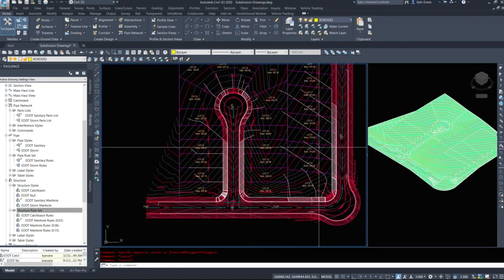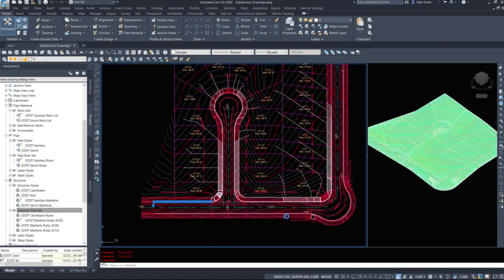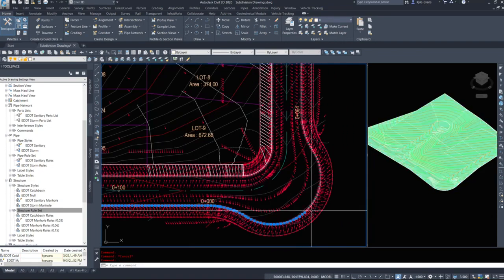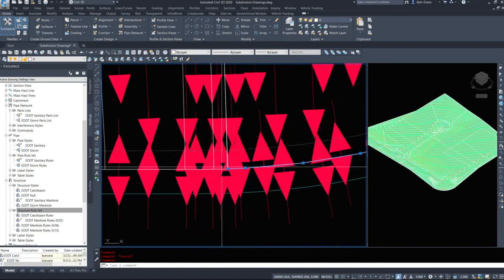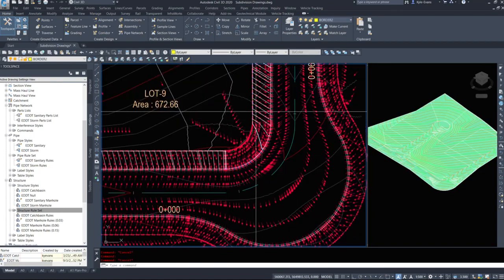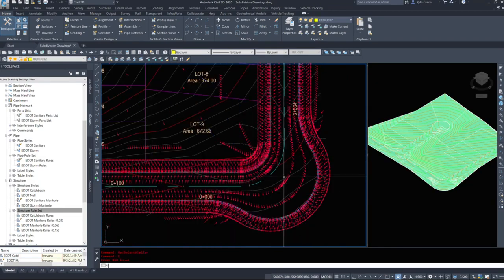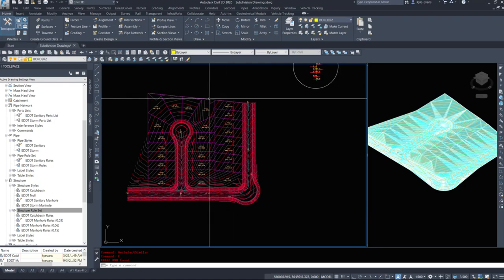All right, I have my escape back. So I'm not going to use the water drop command anymore, but this just shows you that we can see where things are draining. So I will for sure have a catch basin in this location at the end of this line. I will for sure have a catch basin down here. I will also for sure have a catch basin right here. Now I'm going to select similar on these and just erase them because we really don't need them. They're just going to take up space in your drawing.